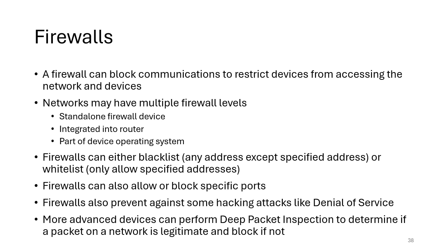So again, when we talk about Modbus TCP, we've got the port, we've got the IP addresses, but we've also got the MAC addresses. So what deep packet inspection could do is look down at the MAC address level and see, has the device been on the network before? Is this a device I want to allow? And it could actually block that device, block that message based on something that's quite low level in that protocol.